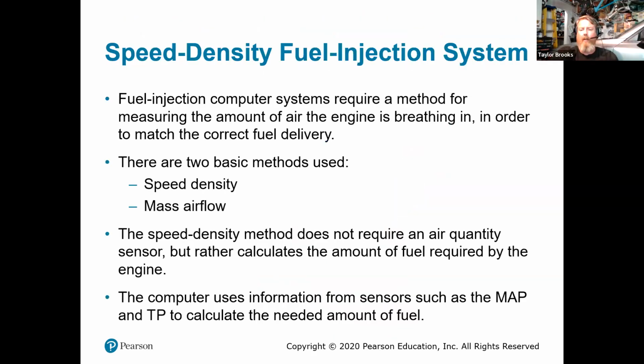Now, there's going to be a couple methods in which we are programming or getting the prediction on how much duty cycle or pulse width we should have for our fuel injector. We've talked about these in the past. It's going to be speed density and it's going to be mass airflow.